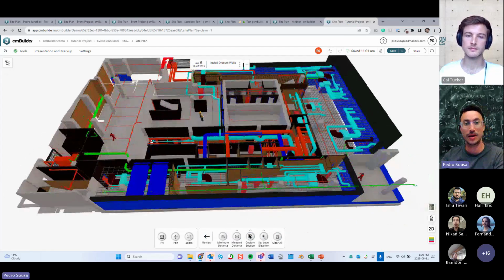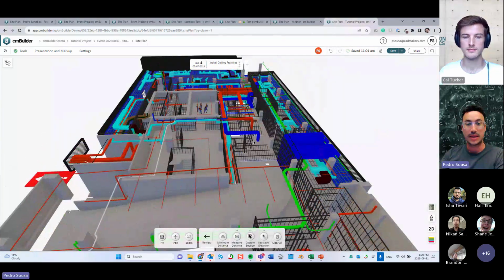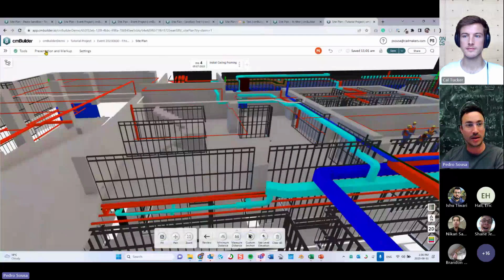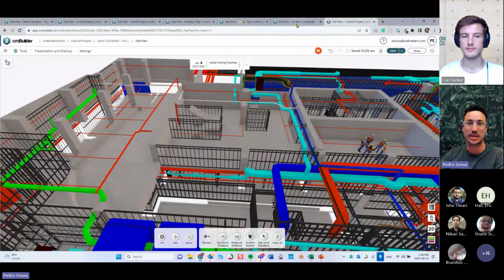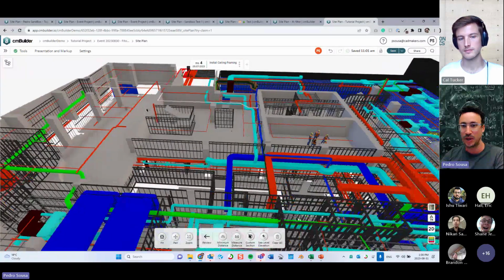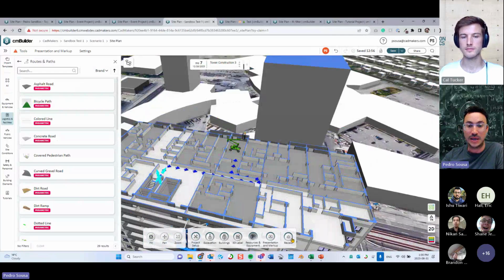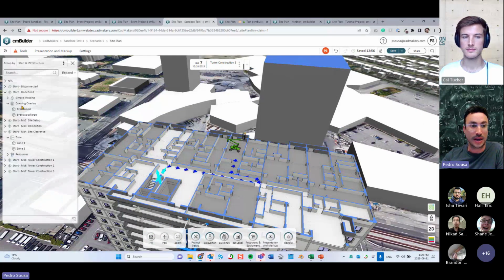Yeah, that's a great question. If the file format that you imported is an IFC, you now have the dynamic tree. I won't be able to show it on the fit out because the dynamic tree is only available on our test environment. But if you do have the model as an IFC, you'll be able to reuse the IFC classes directly from the view, but also you can see all the parts that are assigned to different sequences, because we know that fit out sequences are a little bit more detailed per area and things like that. So it's a better way for you to visualize what is assigned to which area, right?